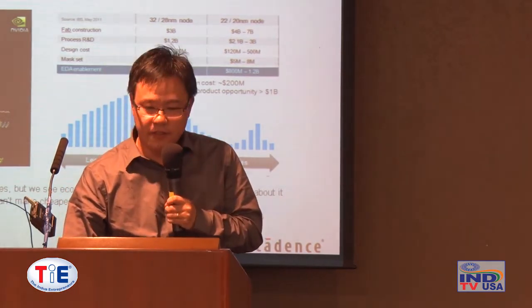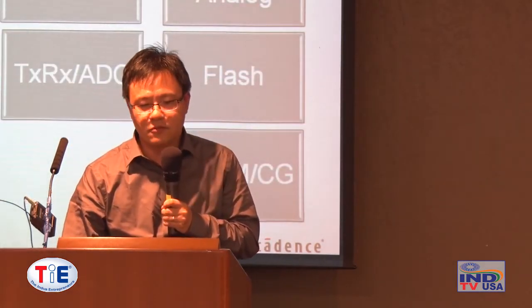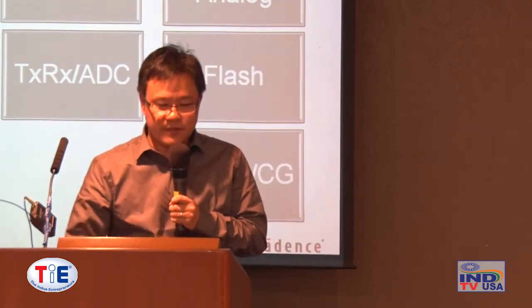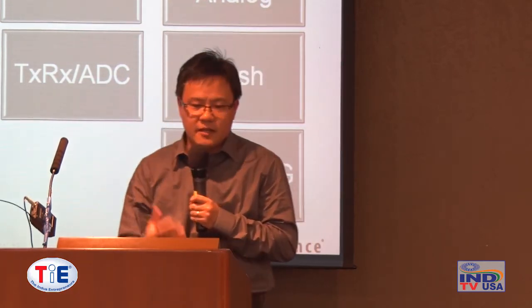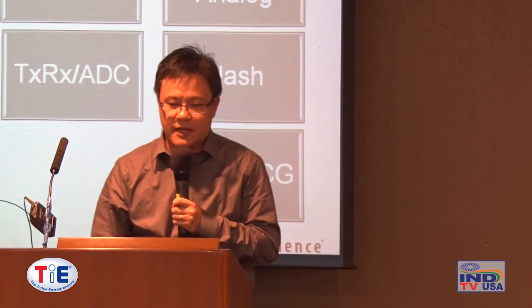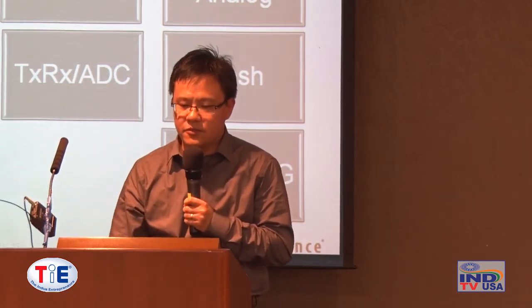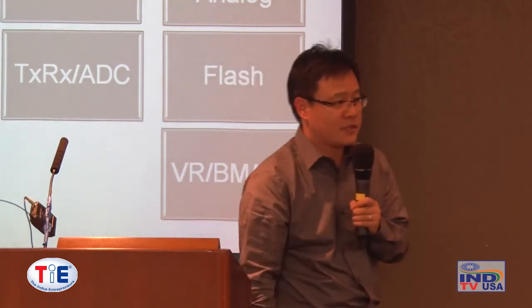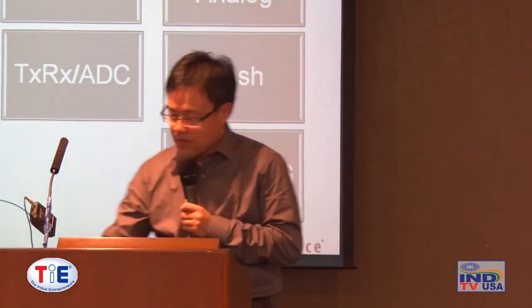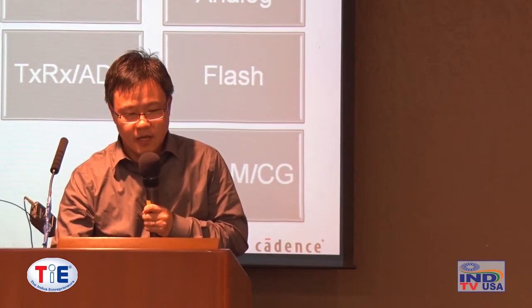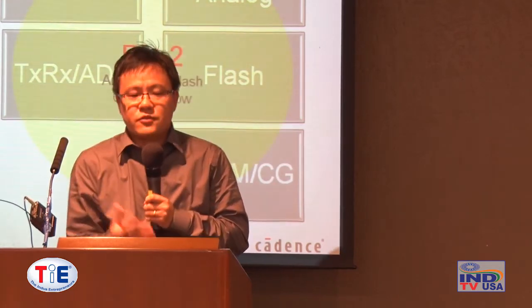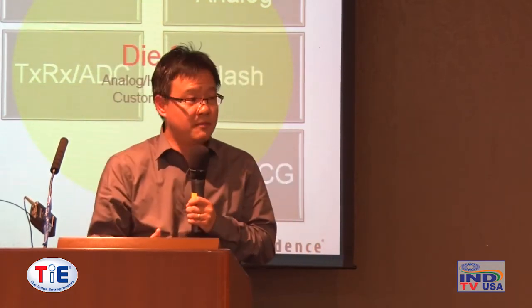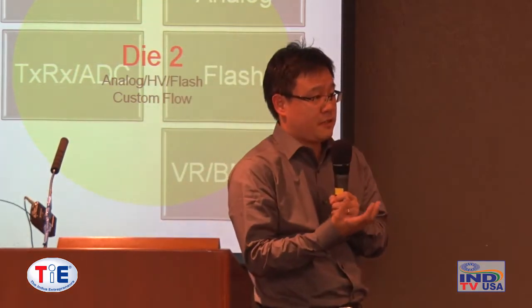We need heterogeneous integration, apparently. I'm going to try to give just an example of what's going to be in IoT. There are sensors and sensor bus and RF, wireless connectivities, low power analog, flash possibly for the higher end one. There are transceivers, power management, and of course you have the processor system, probably very small in terms of silicon area. They're doing the control and DSP. So in a heterogeneous integration, you could possibly put them in two different dies, meaning different process nodes.